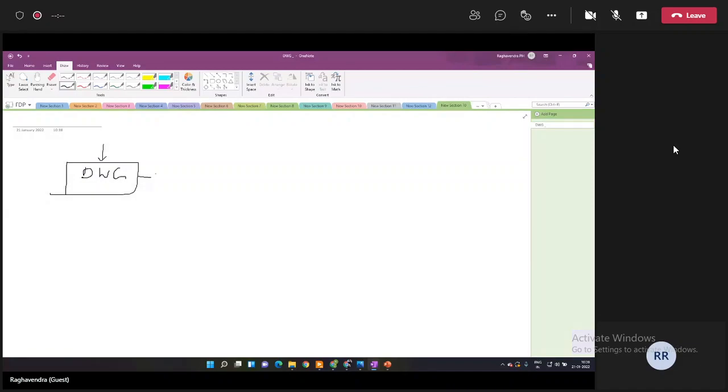Followed by which you have a DAC, sorry, not ADC, my bad, DAC, which converts the digital to analog. And then you have a set of filters. So you have a two-stage filtering process where you have a bandpass filter, you have an amplifier over here, and then a mixer which mixes it to the correct local oscillator frequency that you want. So let's say I want to do it at 3 gigahertz. This provides 3 gigahertz, and then the signal again goes out.